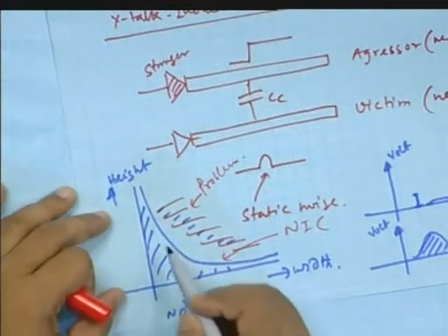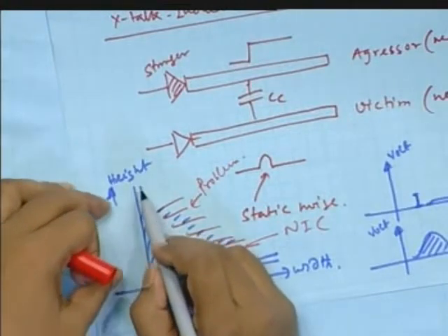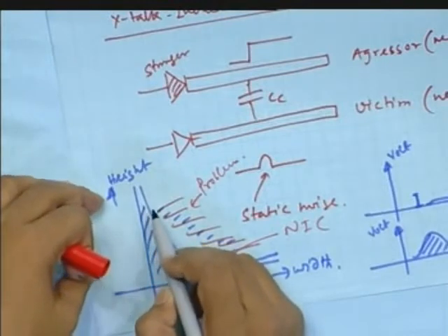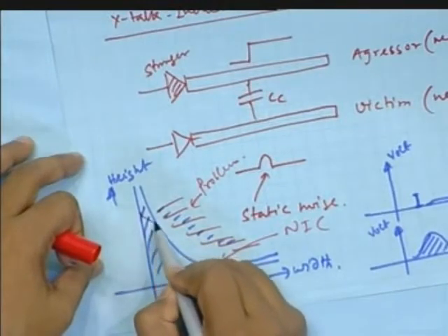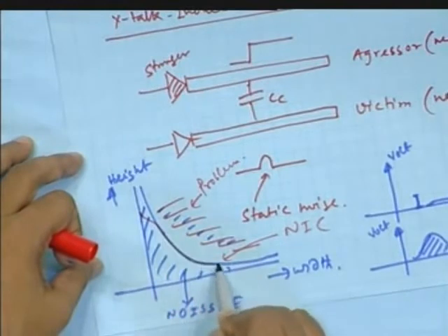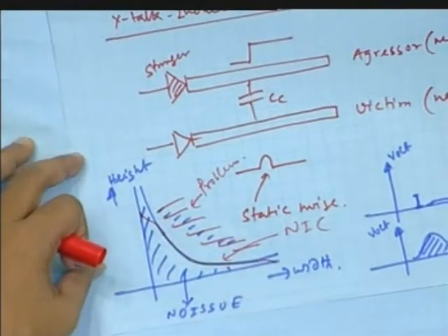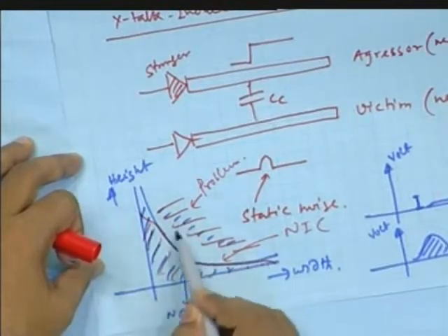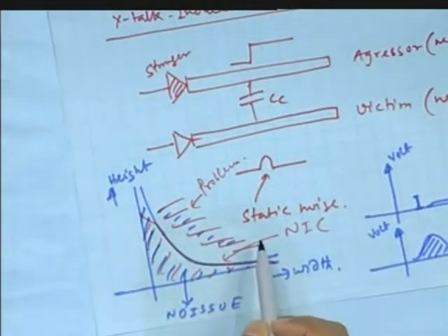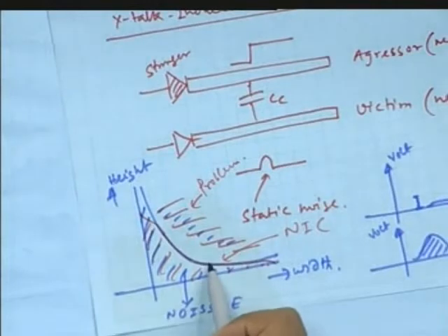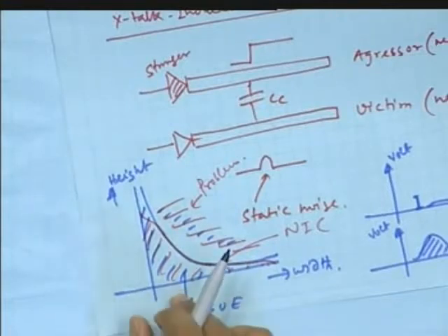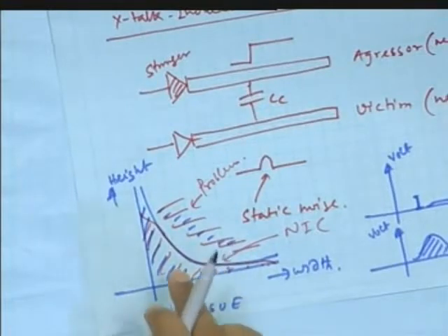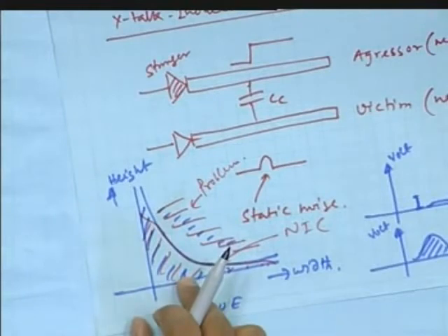See, this height generally doesn't go on after a certain time, right? I mean, it's a theoretical curve. But actually, say my curve is like this. So if you are in this region, there is no issue. If you are in this region, there is a problem. This curve is actually supplied by the library vendor. The crosstalk-aware library should have this characterization.